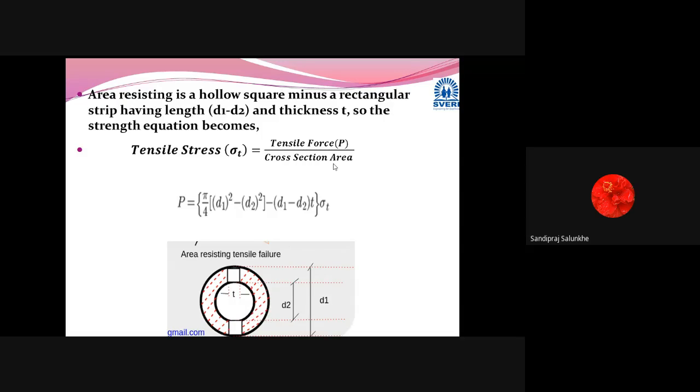For the application, they are going to specify the application, for joining a trailer to the tractor. So we have to collect all the data from the design data book or from previous experience, that how much tensile load has to be considered. Before that, we have to consider the maximum limit of the load that the trolley can carry. From that load, we have to calculate the tensile force.